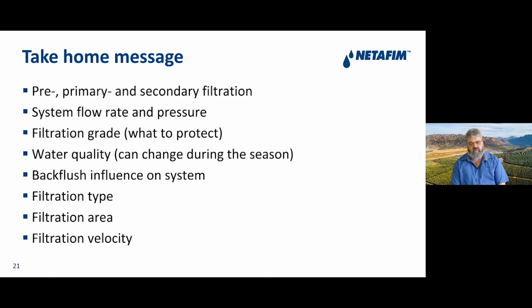Secondary filtration is a very good design, especially when you have a longer distance from your primary to your field. And also today we inject fertilizer through the system. So in that case, it's also good to have secondary filters because the fertilizer in the line stands as food again for algae growth after the primary filter.